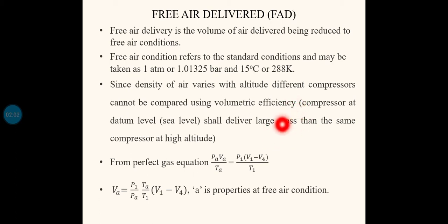At low altitude or sea level condition, the density of the air will be much more compared to the density of the air at higher altitude. So if we calculate the volumetric efficiency of the compressor at sea level and at a higher altitude, we will have different values. So if we want to compare two different compressors, the performance values, like volumetric efficiencies, are to be calculated at the same standard condition. That's why we go for this free air delivery condition.